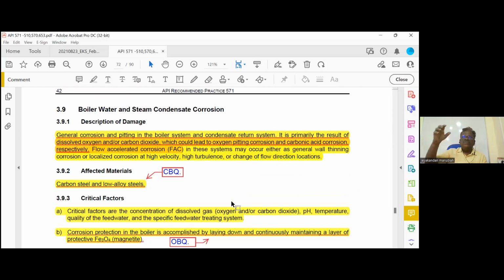Vacuum means we will create a vacuum. There is something called a vacuum box, or you can do the vacuum in a chamber also. There is a vacuum pump. We will remove the air completely. So outside the atmospheric pressure is 15 psi, and inside there is zero pressure. There is no air. So what will happen? Any hole there will be leakage. If you apply a soap solution, the bubbles will come. They will do this only for tanks. Okay, the condenser also they can do for the vacuum test.